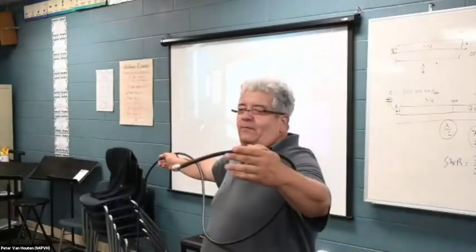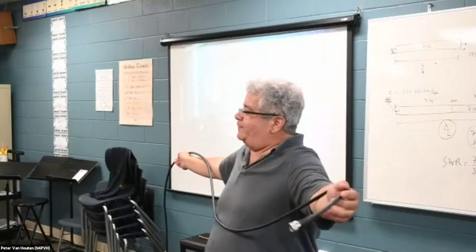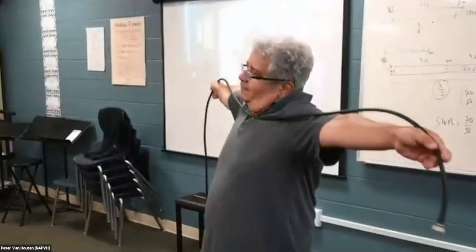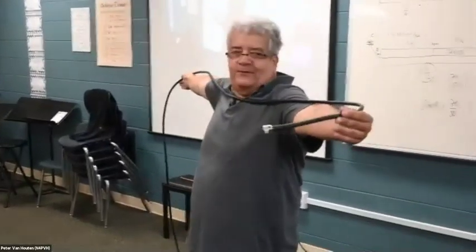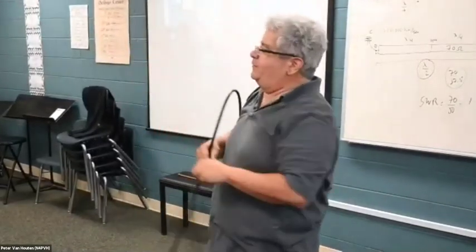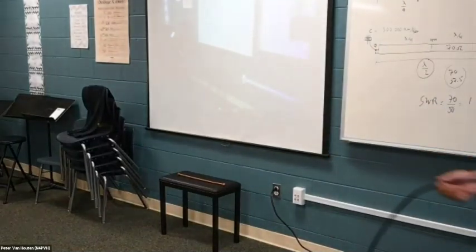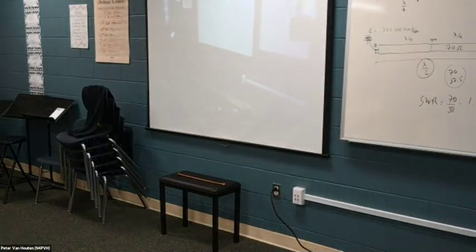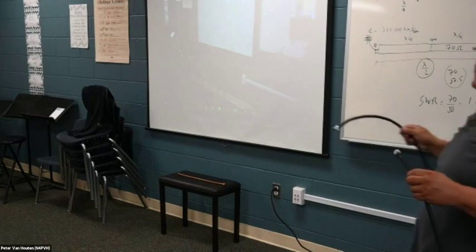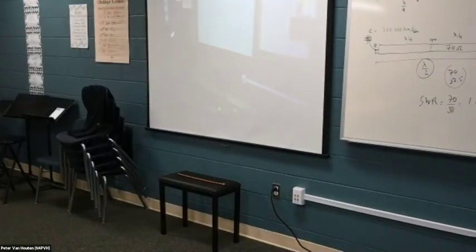So this is, more or less, pretty close to 3.3, 3.4 meters. This is about 1.6 meters, so we have about 320 twice, and then 20 centimeters. It's about 340, 3.4 meters. So this will be pretty close to a quarter wave on 14.2 megahertz. So on which frequency will this be close to half wave?